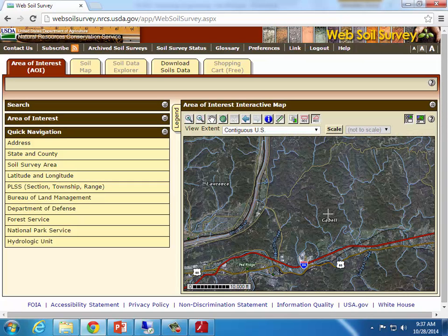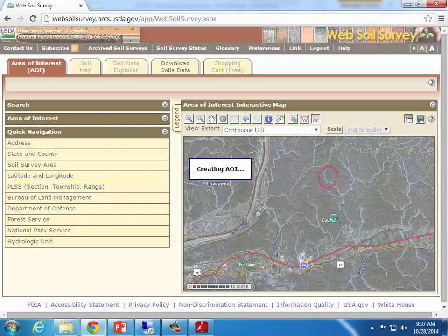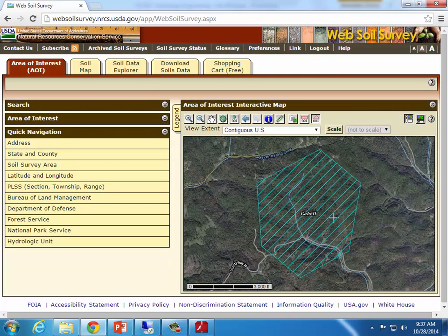So if I went into Google Earth and I found out that my watershed that I'm interested in is over here, then I can use this polygon tool and click around the boundaries of my area of interest, double click at the end, and then it sort of delineates that zone in the same way that it did when I had imported the zip file. So now I can go across these tabs and gather the data that's just going to be within the cross-hatched area that I've defined through interactive clicking.